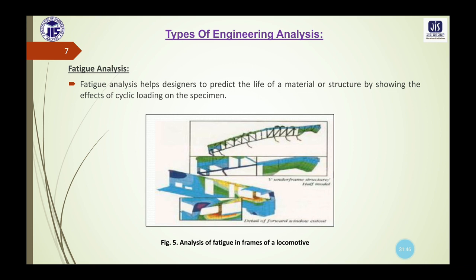Next, fatigue analysis can also be done, and this fatigue analysis helps the designers to predict the life of a material or structure by showing the effects of cyclic loading on the specimen. In such fatigue analysis, it can show the areas where crack propagation is most likely to occur, and the failure due to fatigue may also show the damage tolerance of the material. So optimization and some precautions can be achieved using the software simulation.